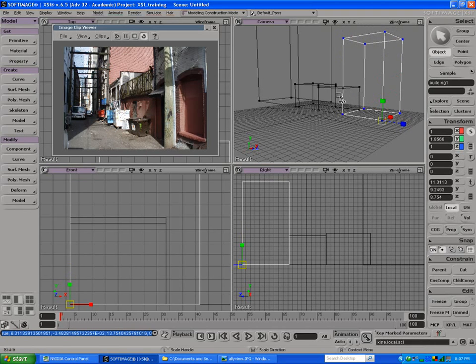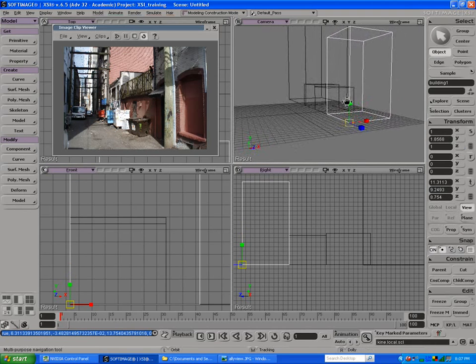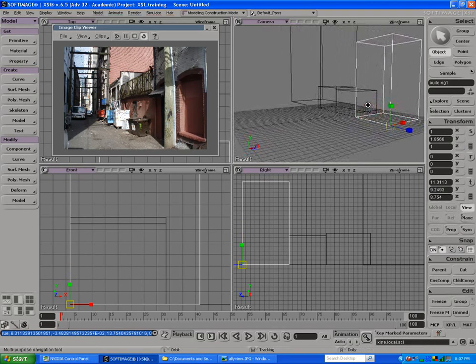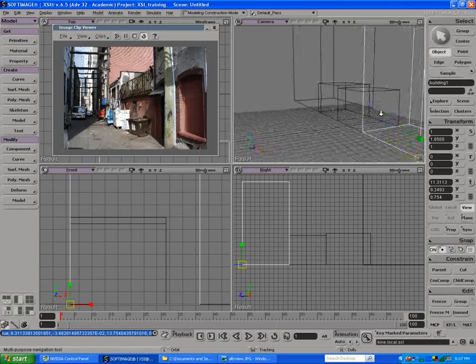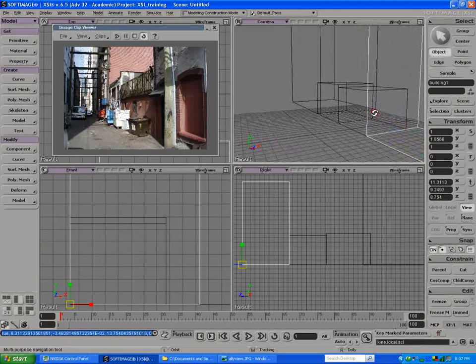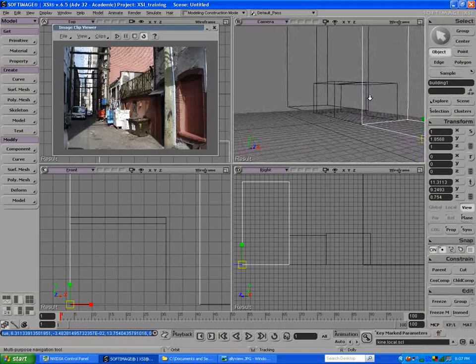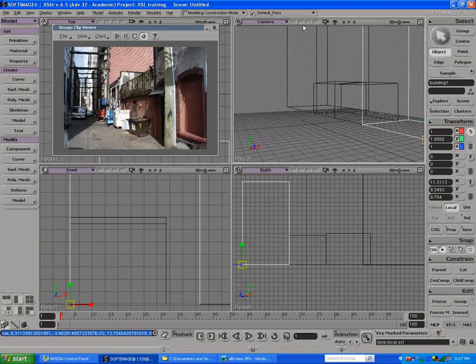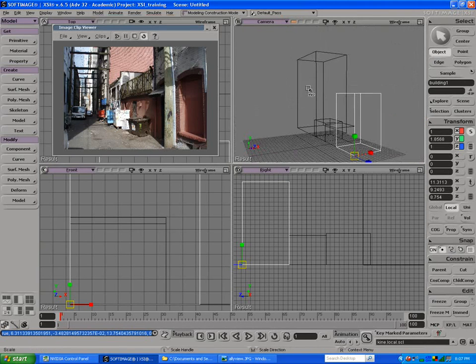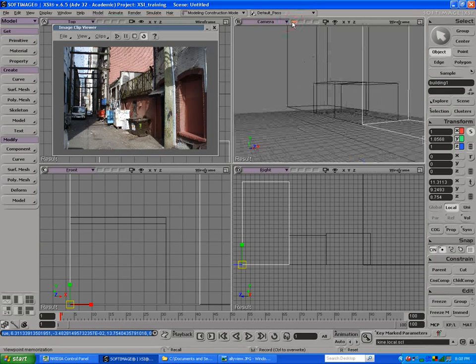So I'm just going to get my camera set up again, more into the camera picture angle, so I can come back and forth. I'm going to go a little bit further out in this case, and then we're going to memo cam. There's these buttons here that allow us to save a camera, so if you middle mouse, it saves it. If I move the camera and click on here again, left mouse, it gets back to it.